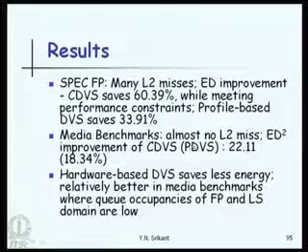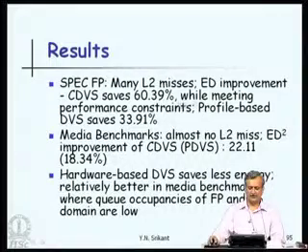Here are the results available for MCD processors using this PetriNet based modeling technique. For the SPEC FP benchmarks, there are many L2 misses, so the energy delay product improvement is very large. Our technique saves 60% energy while meeting performance constraints, whereas existing hardware profile based dynamic voltage scaling techniques save only about 34%.